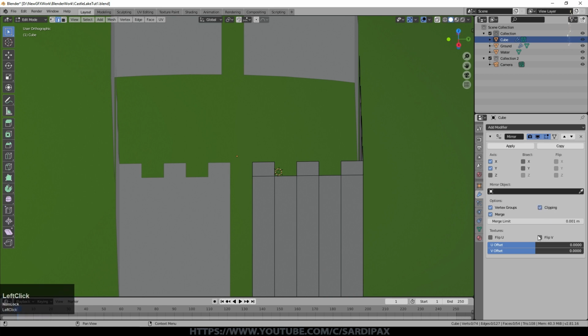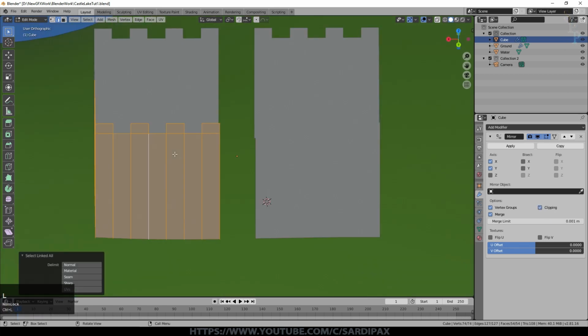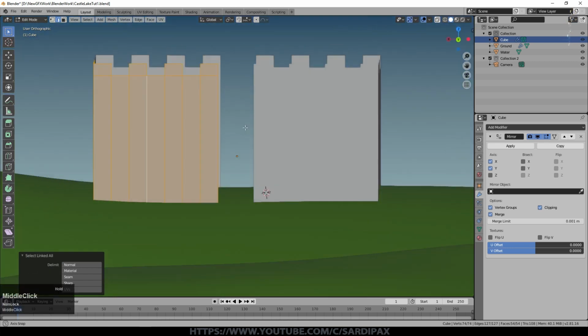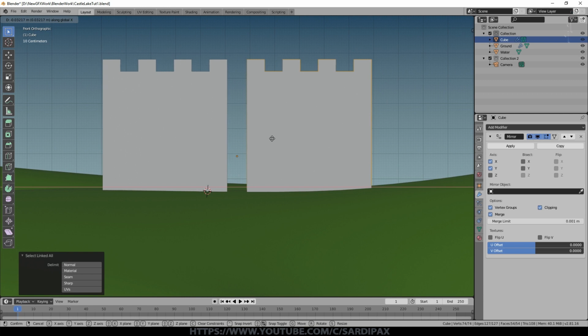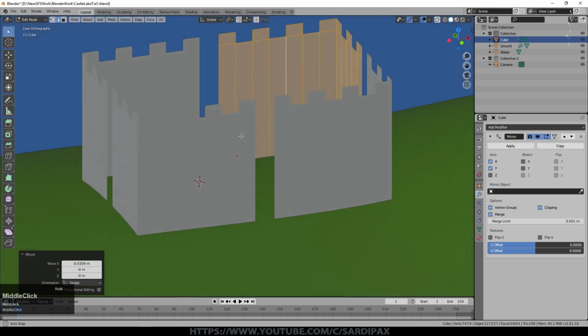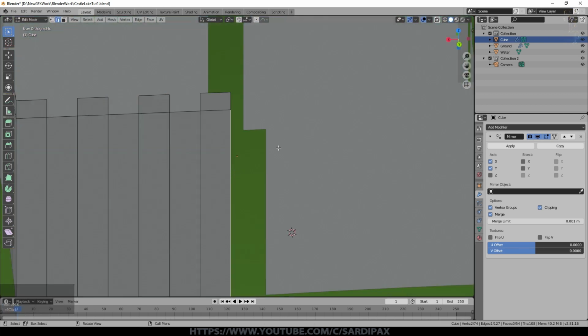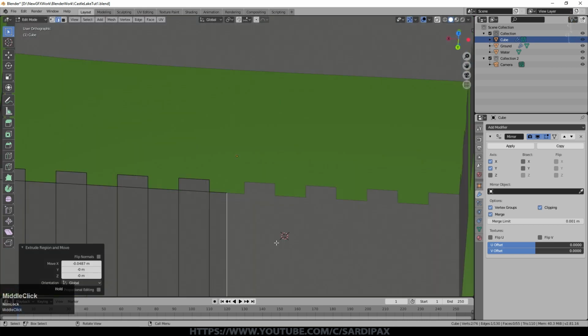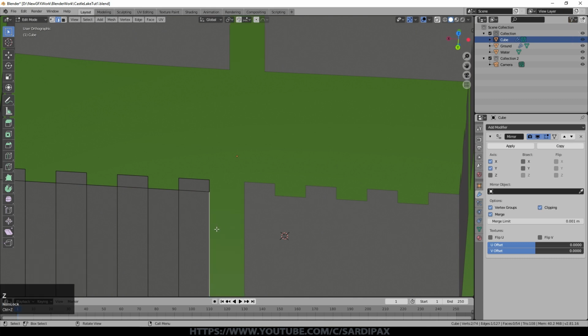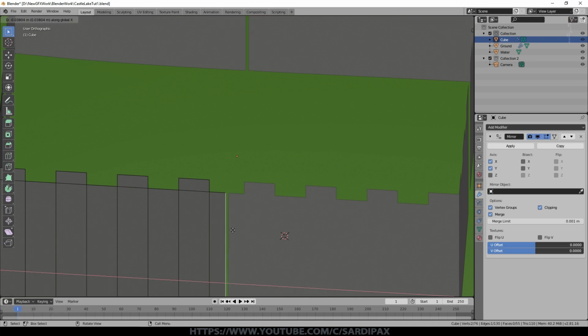I'm going to turn on clipping. I did Control L there to select everything. For this axis, that's actually a bit too wide. So G X, and we'll come to about there, and that'll be about right. Obviously there are more accurate ways to do this as well. So I've now just selected that edge and I'm going to go E X, and that will allow me just to close up that point. And you can see we've got our castellation there. We can make it a little smaller in a minute. We can even leave a little gap if we think it's a little bit too big.